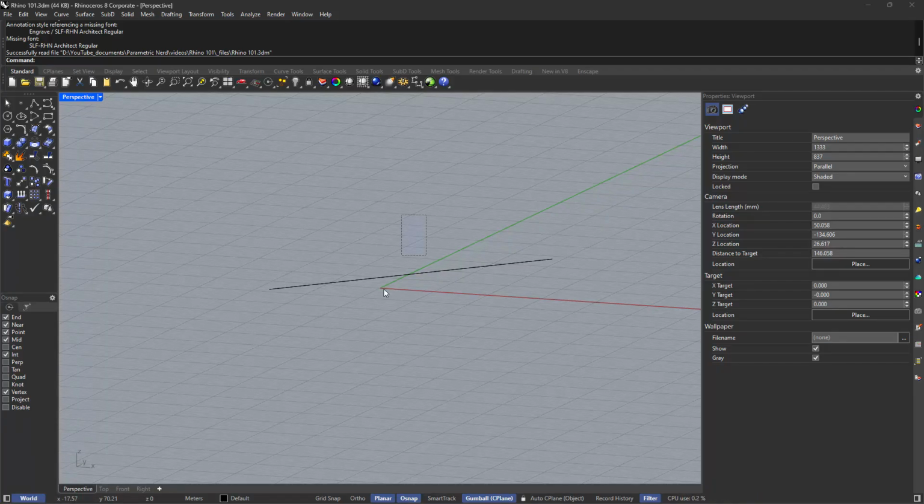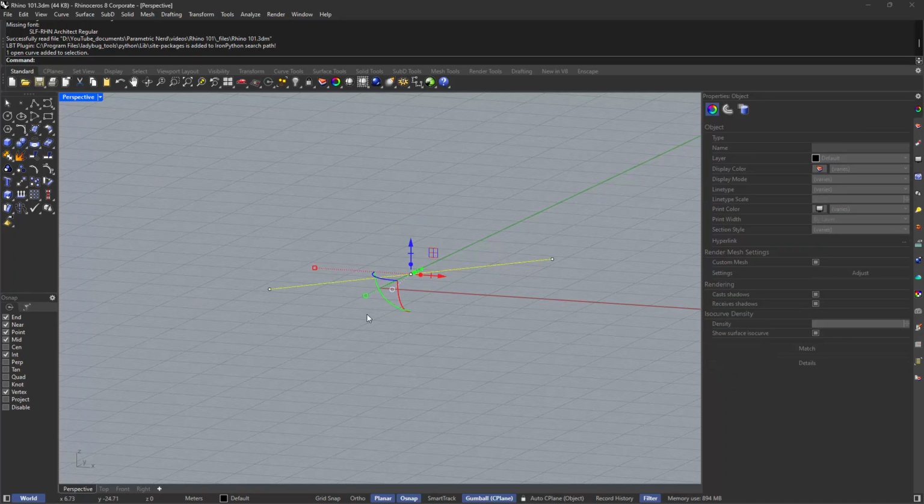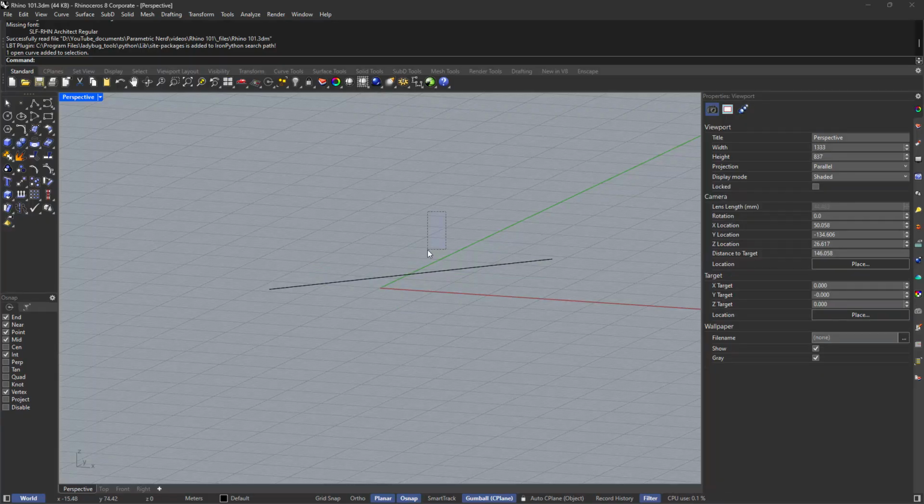If you want to select this line, just click your mouse and draw a rectangle. It's selected. As you see, our rectangle outline is dashed shape. So you see it's dashed. If you move your mouse to the left, it's dashed. And if you move your mouse to right, it's simple line. And you can't select your line this way.